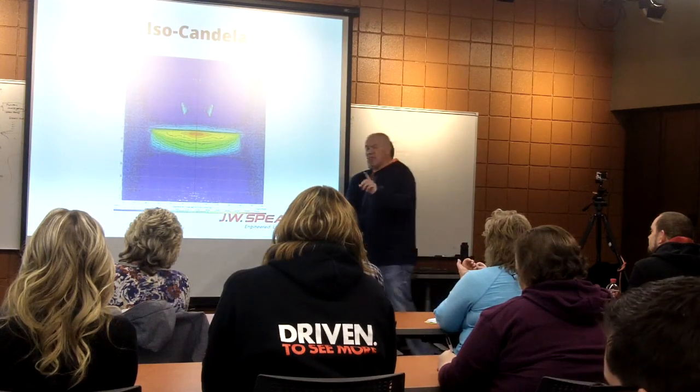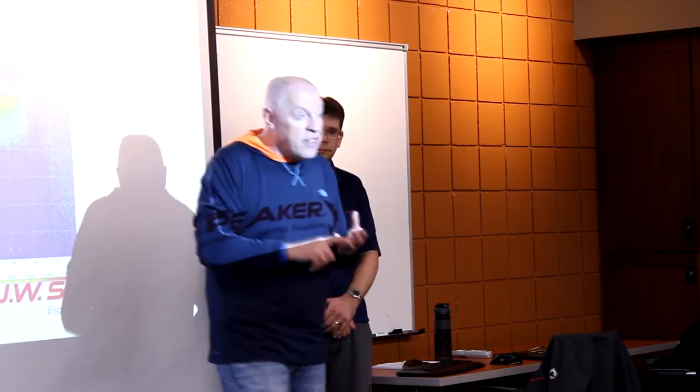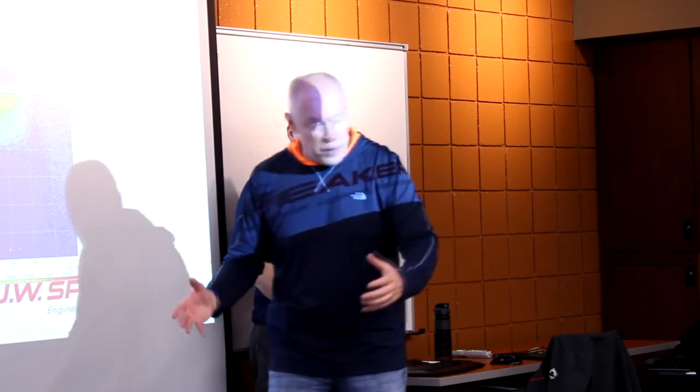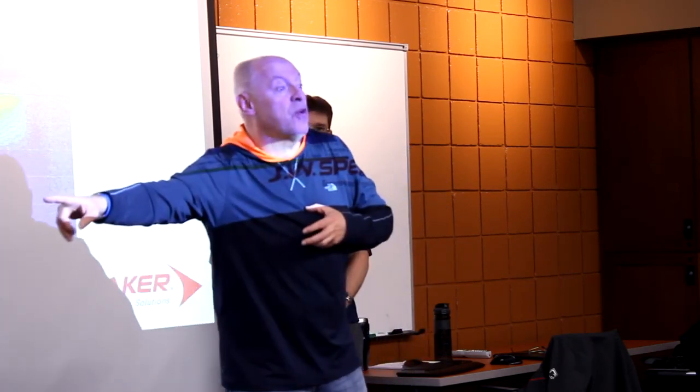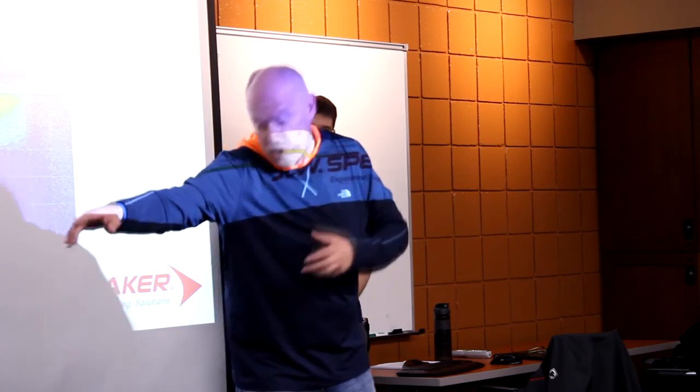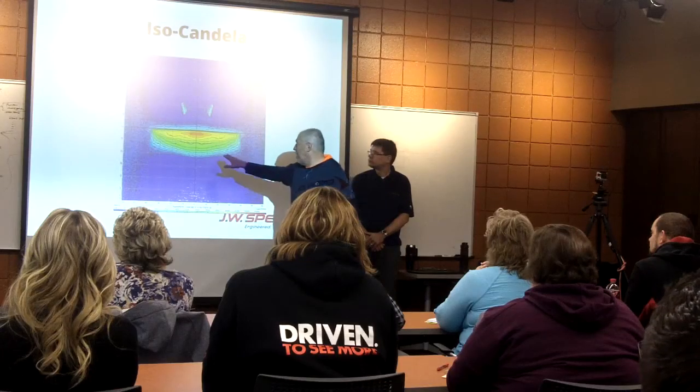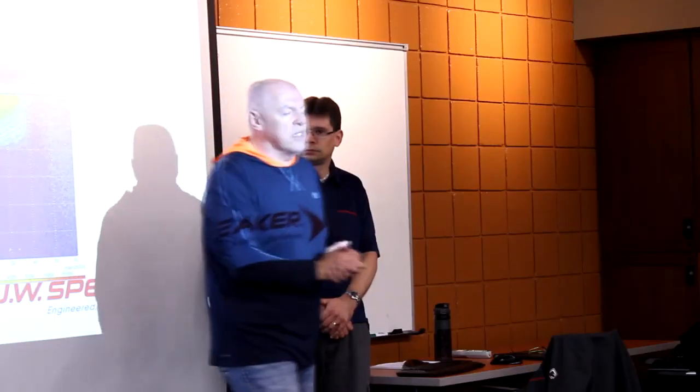Okay? I'm sorry, intensity, foreground. Foreground means how wide vertically your pattern is. This is a very important parameter for motorcycles and ATVs, because you're open and you don't want to see your light starting 5 meters in front of your vehicle. So basically that is the foreground light, and it's usually getting around -20. That's the number, which is good.